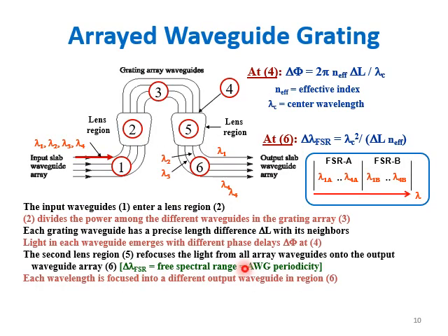So this is another pattern to be represented, the arrayed waveguide grating. This is also called phased array based devices. Normally this phased array based device is done with the help of the arrayed waveguide grating. This is the top view diagram of a typical arrayed waveguide grating and the designation of its various operating regions.